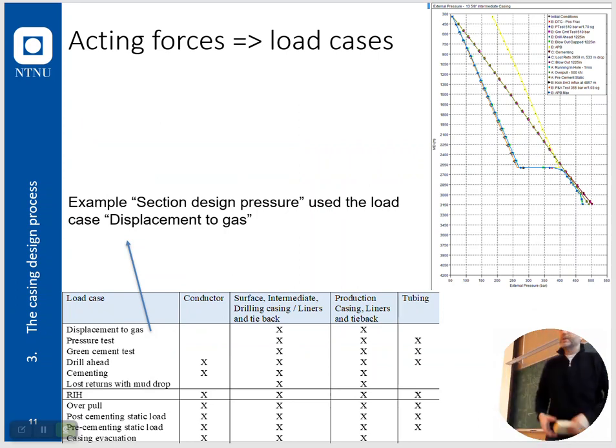I just had a sneak peek in. The drill ahead is basically just to uncover what the new mud weight is going to do. Normally what you're afraid of is that if you change your mud weight drastically, you will have different pressure regimes over your casing that you just set.